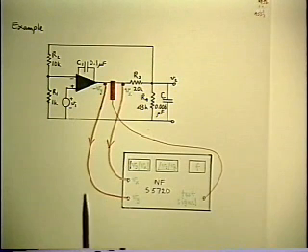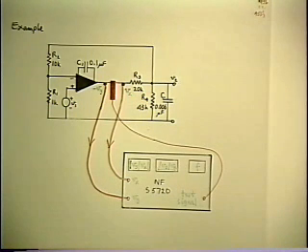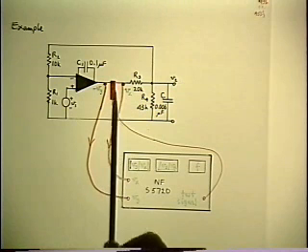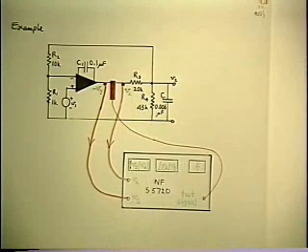And you get 2.5 or 5 volts across that piece of copper foil. And there's nothing weird about that. So you needn't be concerned about getting a few millivolts across a centimeter of a skinny wire. The analyzer has no problem at all in picking it out.